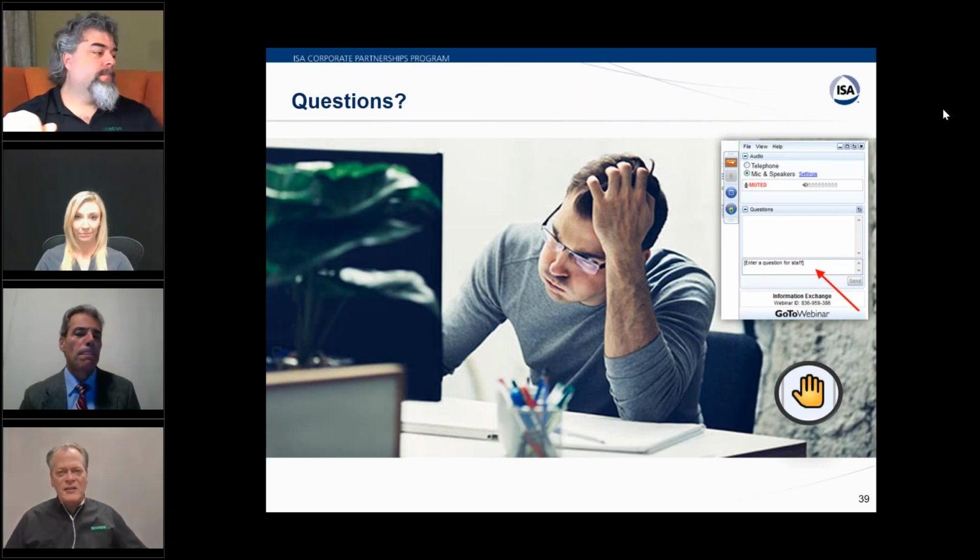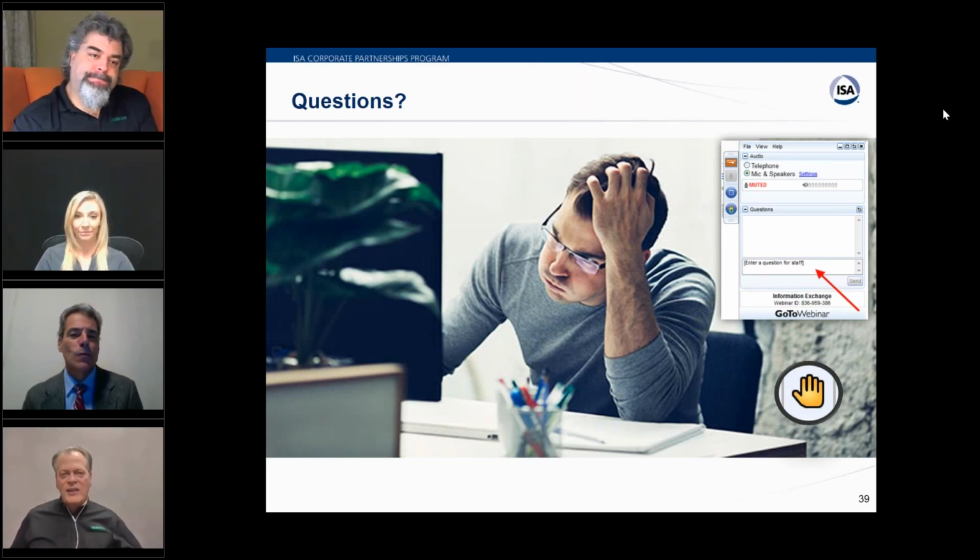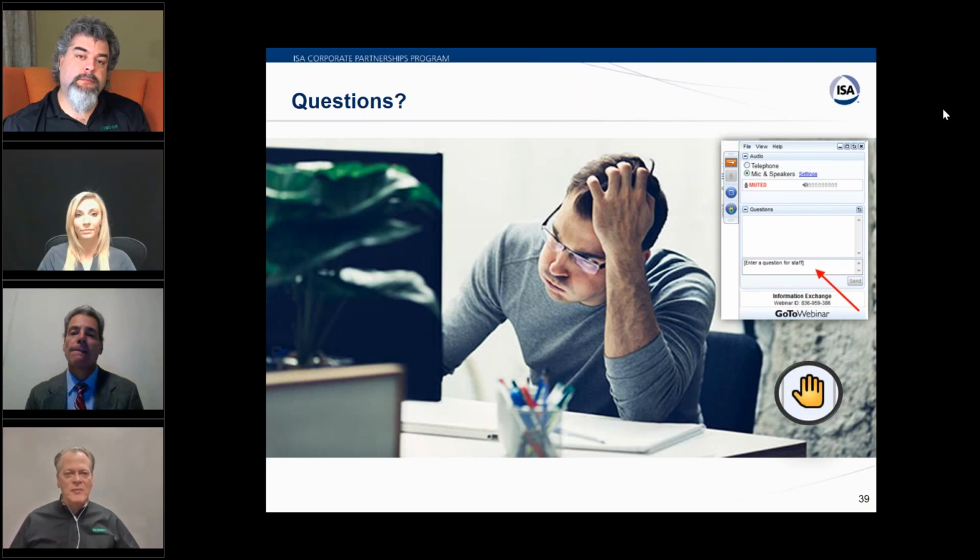Well, I'll take it. I don't like that because you're not checking reality. Why don't you just disconnect the sensor and use a little simulator and simulate 4 to 20 into the system?